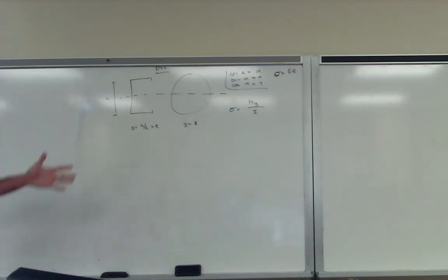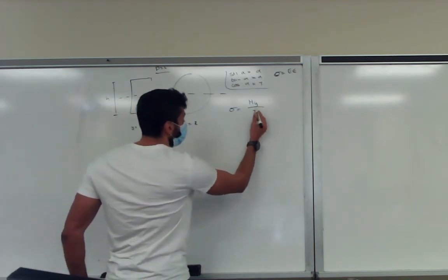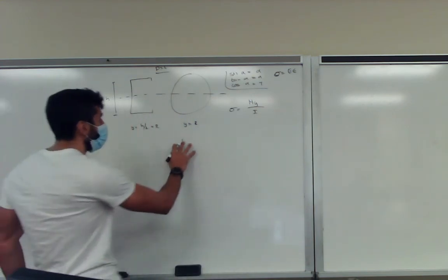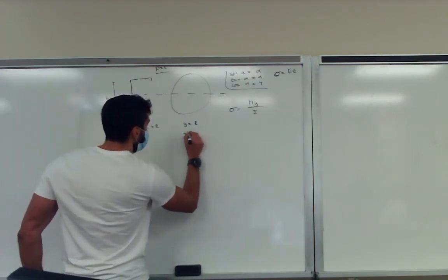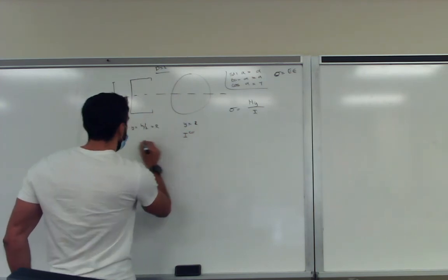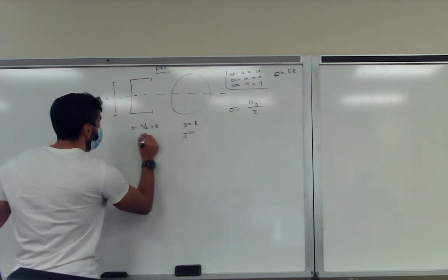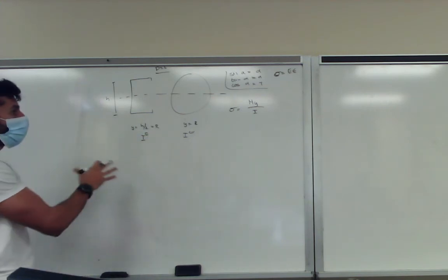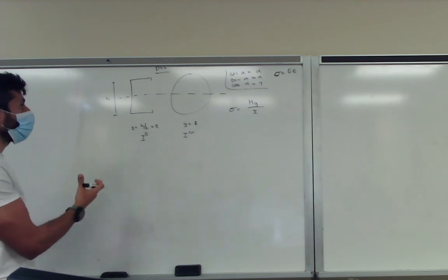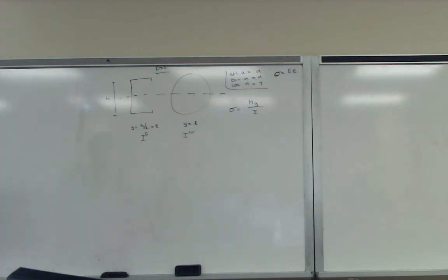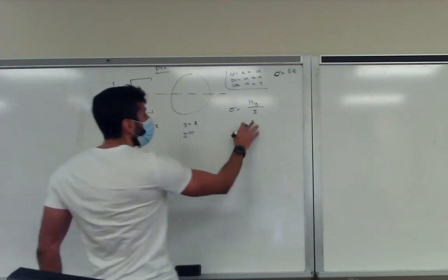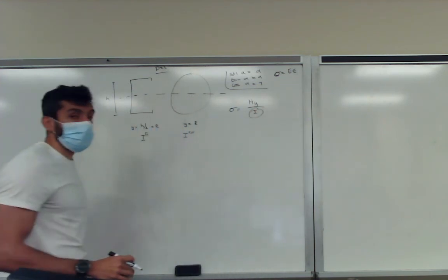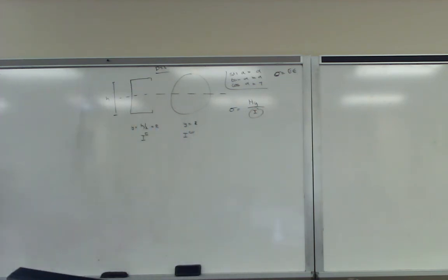So how do you determine which of these two structures will be more efficient in carrying bending? The applied moment is the same, so the moment of inertia will have an effect. So we compare the moment of inertia of a circle versus the moment of inertia of the C beam. As an engineer, to determine which property is better, you look only at the moment of inertia of the cross section. That will determine which cross section is the best.